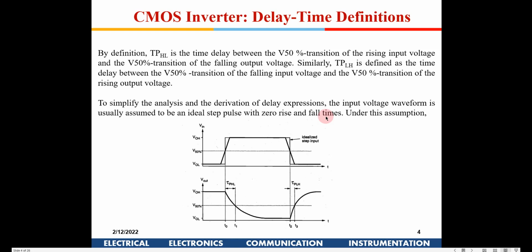So in all, when you make a matrix, there will be a total of 27 different combinations, and in each of these combinations you should clear the minimum set parameter. Whatever amplifier you might have made, which has a certain bandwidth and gain, the bandwidth and gain should be above the minimum value in all these 27 corners.